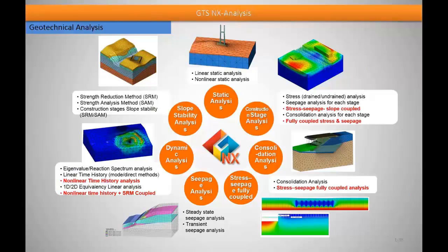Now talking about the GTS NX capabilities, you can see that in the static analysis it has both linear static as well as non-linear static analysis. Also in the construction stage analysis you can see two highlighted things, that is the stress seepage slope coupled analysis. Basically with MIDAS GTS NX, you can now consider the simultaneous effect of the same. Let's suppose if the seepage is taking place, how it is affecting the stress simultaneously could be studied. So a very real ground simulation is possible, and so is true with the stress seepage fully coupled analysis.